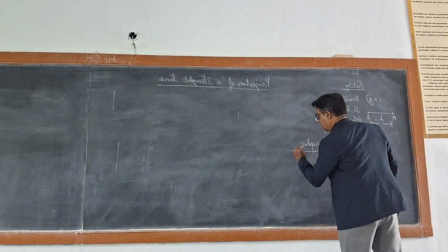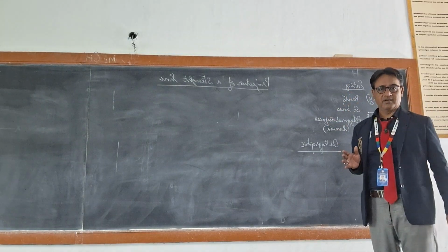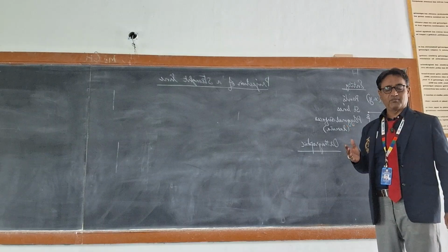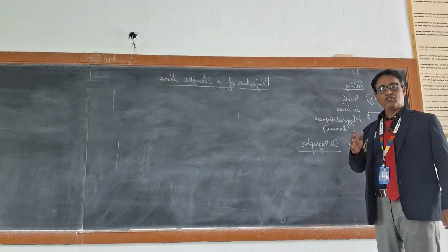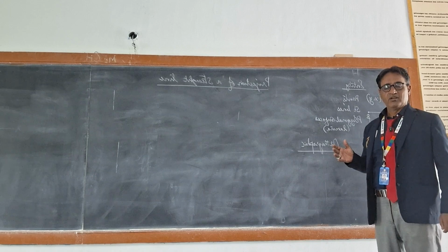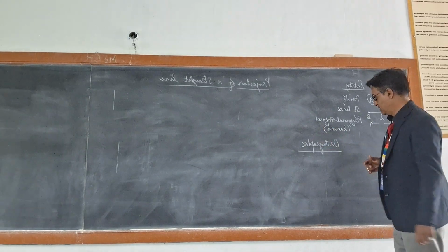That is, the views of the object or the entity which I have listed here will be projected onto perpendicular planes, and all those projectors, which are imaginary lines, will also be at right angles to the projection plane.